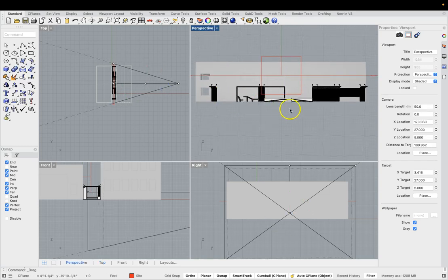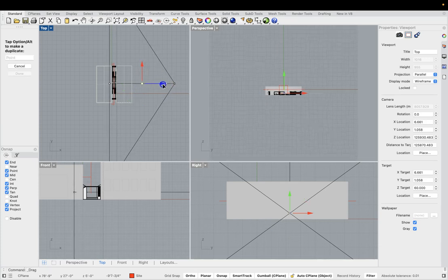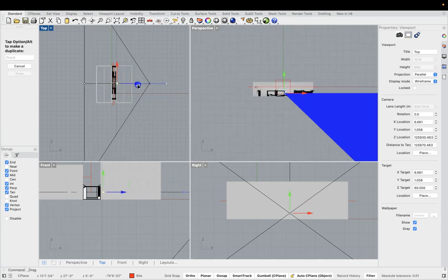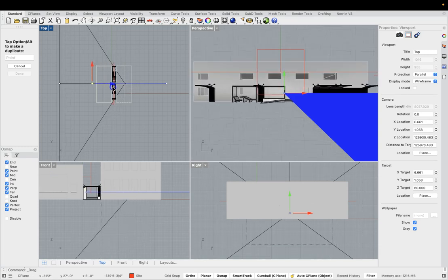But also, we understand from the winter quarter the idea of perspective and field of view. This is actually a very nice field of view, this focal length, to model with, but we might want to play with a more dynamic lens. So I'm actually going to bring this out to something like 10 millimeters, which is a very wide angle lens and very distorted on the edges, but can create a lot of drama. So as I come and walk in, as you see, I still have quite a bit of the building set up.